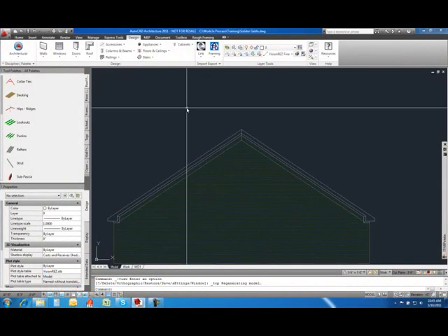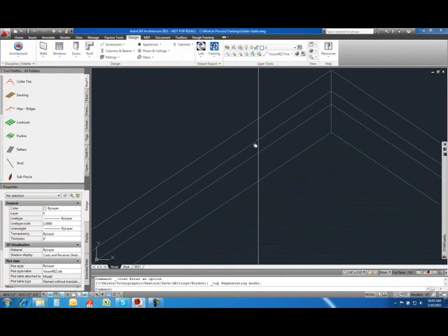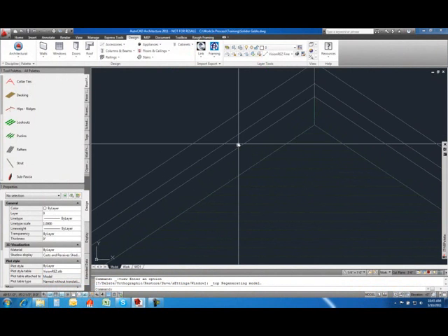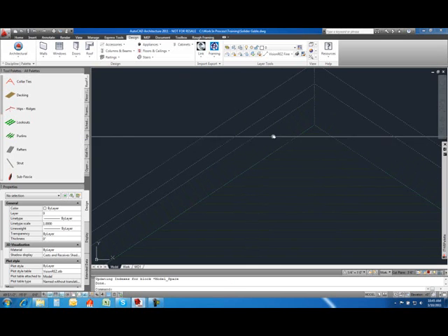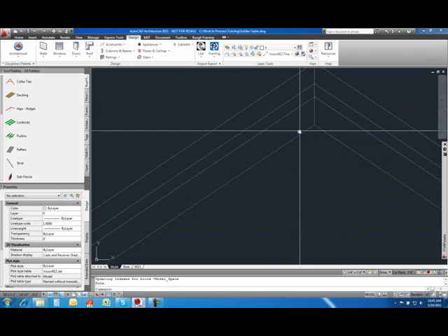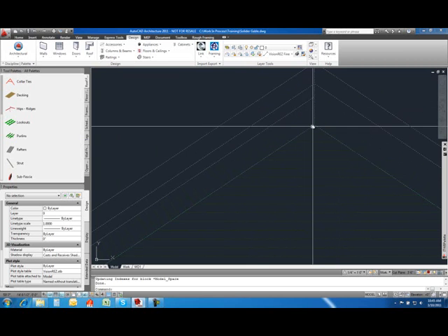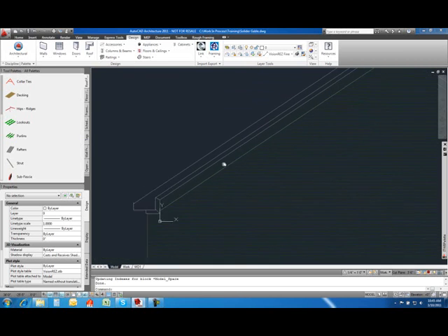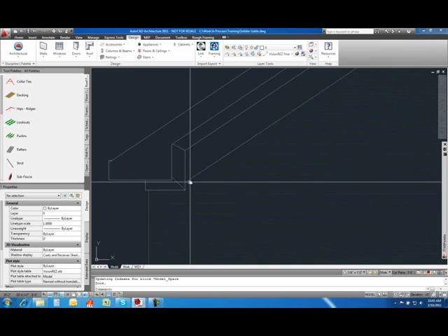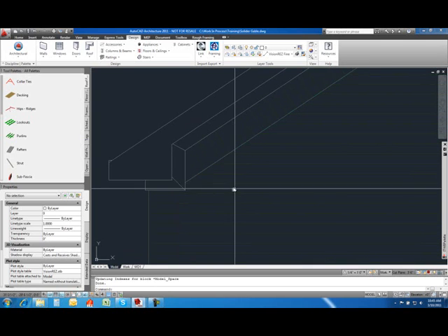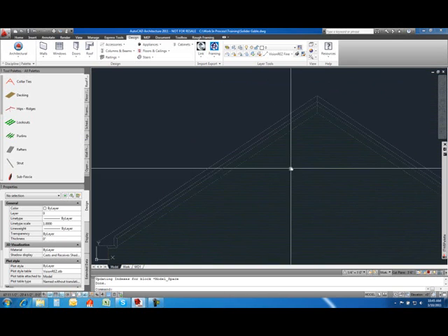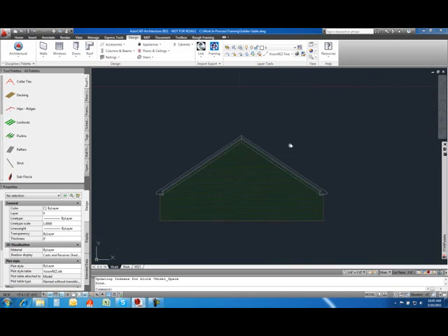What we'll do now is actually make a common condition that you'll see on most generated elevations with a brick gable, and that is a soldier course right underneath the frieze trim, with the joints perpendicular to the slope of the roof, mitered here at the top, 8 inches wide, maybe a little bit over an inch or under an inch thick to give that nice relief. And that's just a common look, and also when it hits a vertical transition to actually terminate it there. And that's a common trim piece that you'll see in a generated elevation.